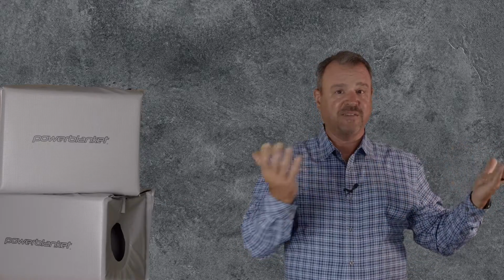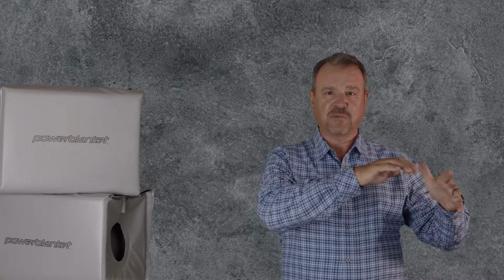And one example is, I had a customer who had a lot of very large 365 kilowatt circulation heaters vertically installed. So the terminal box was on top. Well, while these units were being stored in the yard, they left them in the open air and the terminal boxes were taken off. And they filled with water as rainstorms came through the winter. When springtime came and they decided to install these in the process, they rolled the terminal box over and bolted them shut. So when commissioning time came, they didn't work.